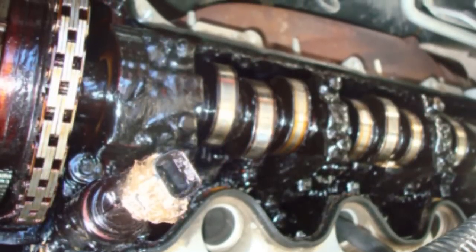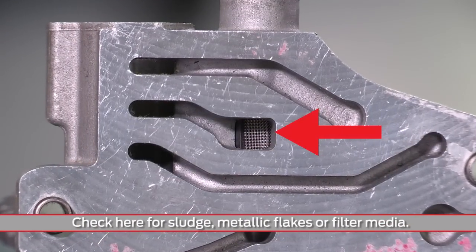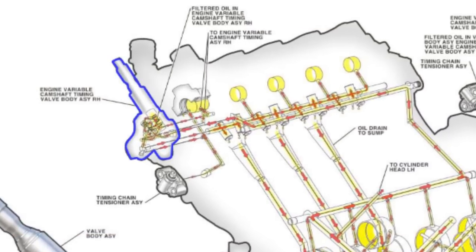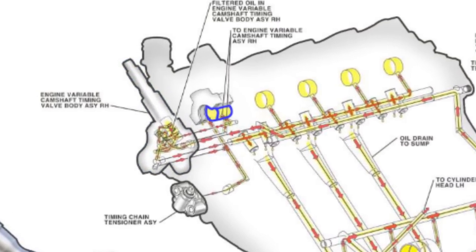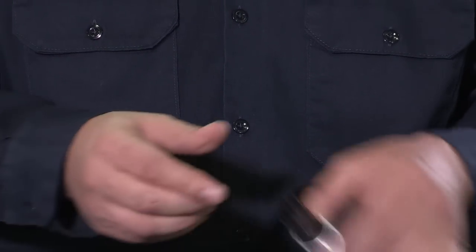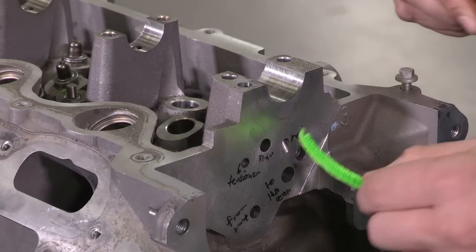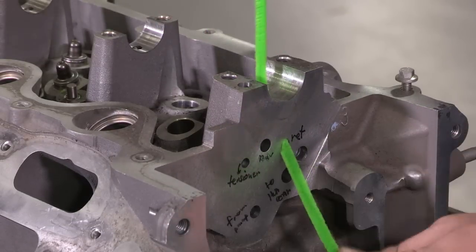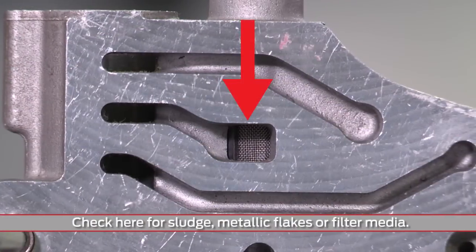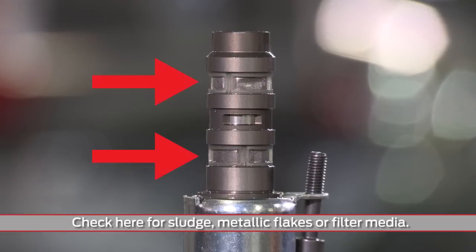Also, check the cylinder head and VCT valve body for sludge, metallic debris, or filter media. The VCT valve body assembly is fed oil from the number 1 cam bore. You can check inside the valve body assembly, the VCT solenoid, and oil passages within the cylinder head to verify either metal, sludge, or filter media are in the system. Debris or sludge in any of these locations can cause the restriction of oil flow.